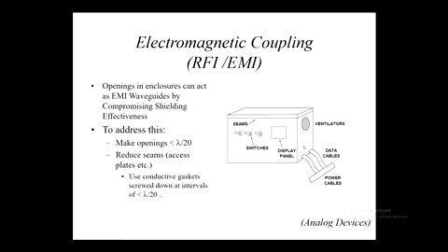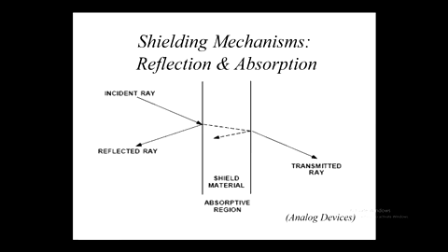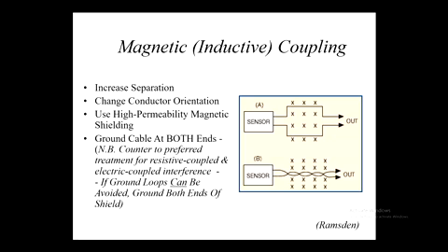We'll flip them through 90 degrees so that they are transverse to the plane, and that way there's no intersection of a field across the loop anymore. So that will minimise the induced magnetic field. We can use forms of shielding with copper or mu metal.